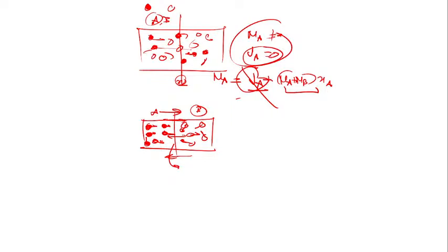And if you want to measure only the flux of A, Na, in this case, is the total molar flux of A because of both contributions or only one contribution? My dear student, in this case the flux of A is because of both contributions. One is because of the difference in concentration, and the other is because of bulk flow, because every molecule is moving. Yes, that is J plus Na plus Nb into Xa. Clear to you?